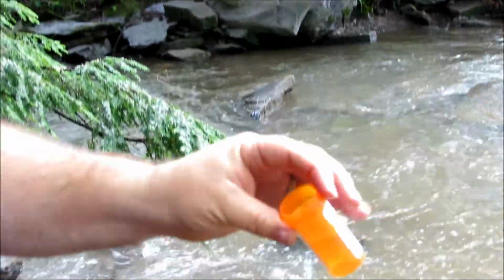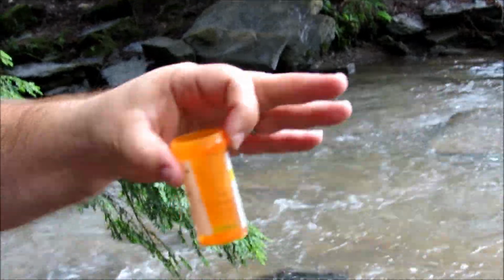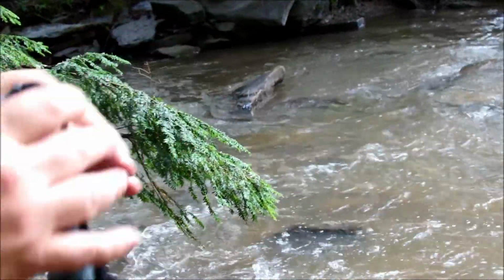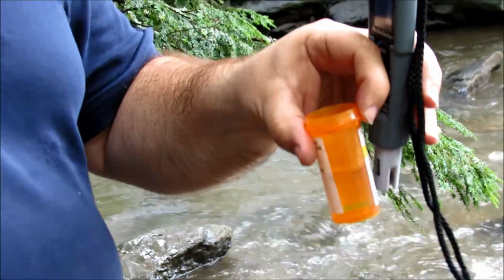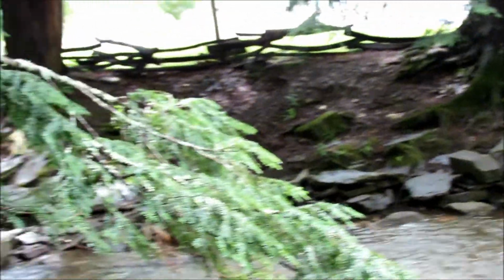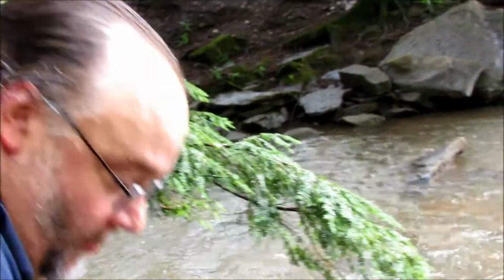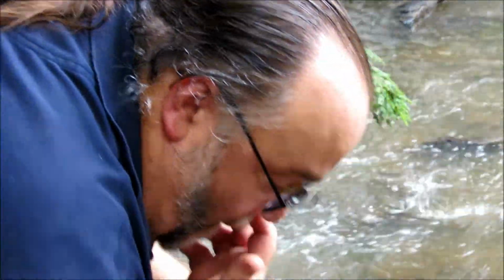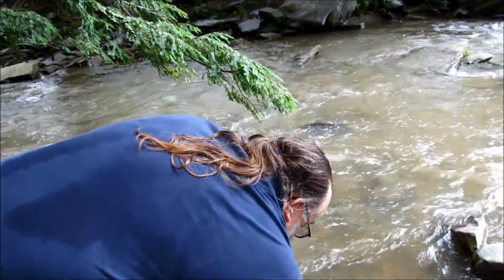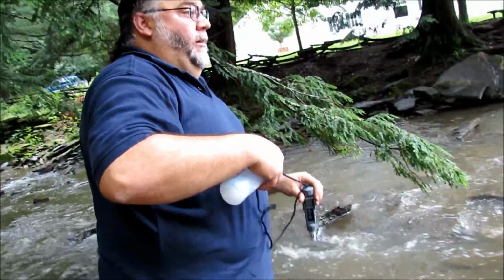And then this is basically a salt solution, so I would never throw it in the stream. I'd go away from the stream and put it over there. Can't you reuse it and put it back in the box? No. You never want to reuse standard. You run the risk of contaminating the standard, and then you're faulting all your data on a standard.